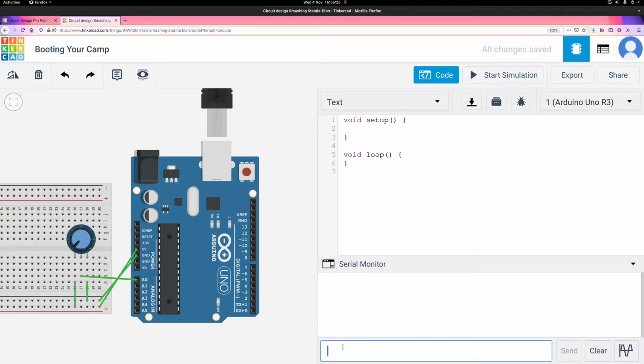In the real world, this signal is sent over this USB cable, and the serial monitor is on your computer. So you can read it on your computer from the Arduino IDE, and you can see what it's outputting. It also has a graphing feature, which is kind of cool, but not something we'll probably play with extensively. Well, actually, we'll be able to play with it in this example, I think. Stellar. All right, so what we need to do is set up the serial console.